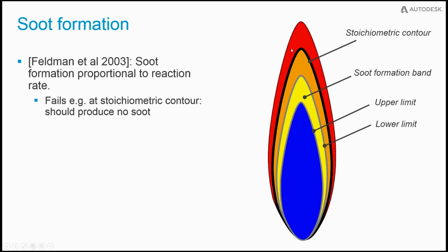I'll come back to what these individual bands mean later on, but this is the visual height of the flame, and it's yellow to red due to the glowing soot. And in the middle here we have the region where the reaction takes place, where we only have the blue flame but no soot. So the stoichiometric contour here, outlined with a wider line, is where oxygen and fuel react, and all oxygen and fuel react to form just products.